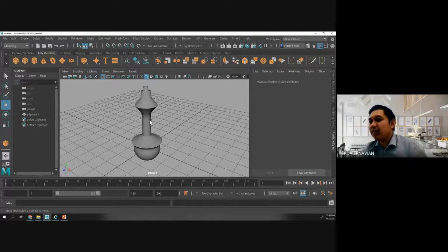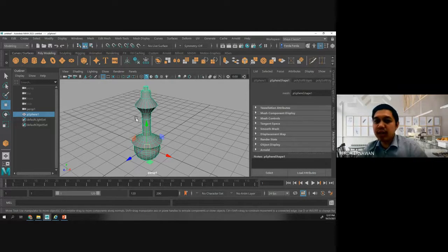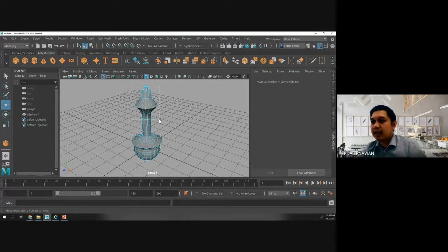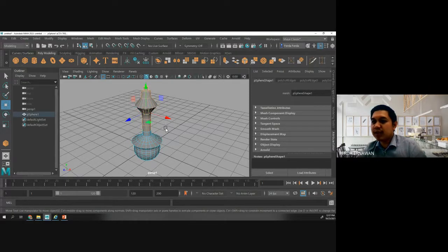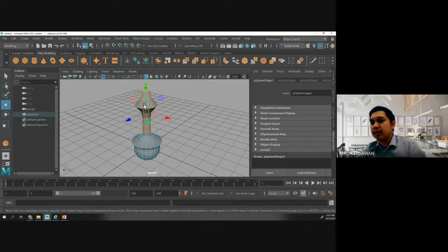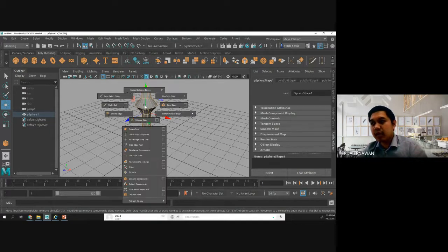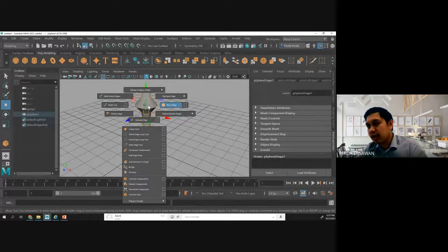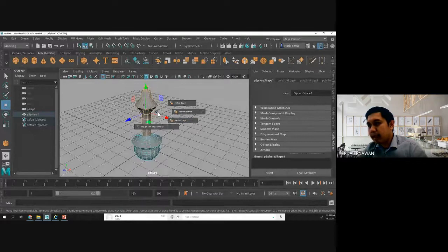Thank you. If you wanna make it soft and hardened, you are in the object mode now. So what should you do here? You have to change into edges here. Edges, and then I can select this area that I want to make soften, for example, until this. So you just press and hold Shift, and then right click. Choose the soften harden. You can see here soften harden edges. This area, then you can choose soften edges.